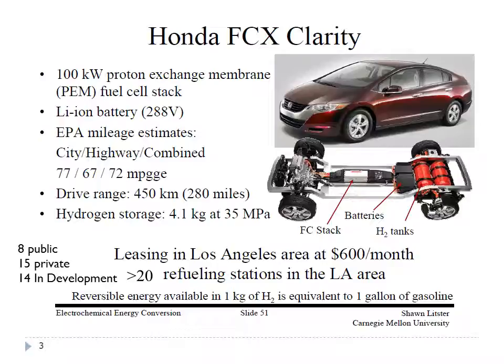So it's a fuel cell and battery car. It's a hybrid. And on all these, not only are they going to have fuel cells and batteries, they're probably also going to have some kind of capacitors, so that the capacitor gives you the very quick response, batteries give you stuff on the minutes, and then your fuel cell basically gives you the hours of range.